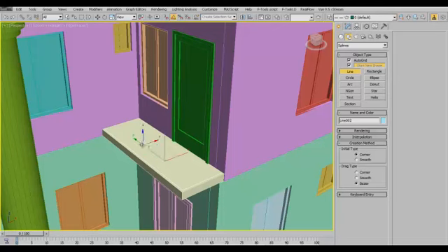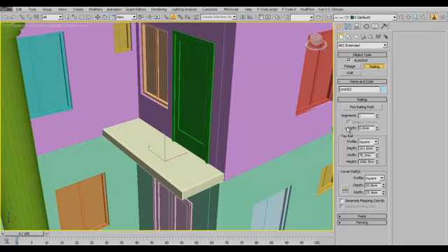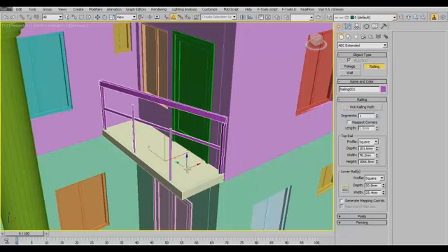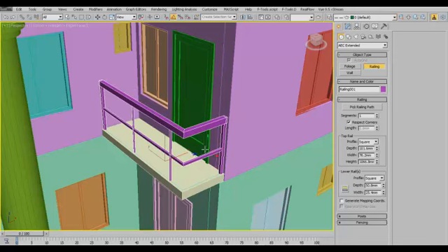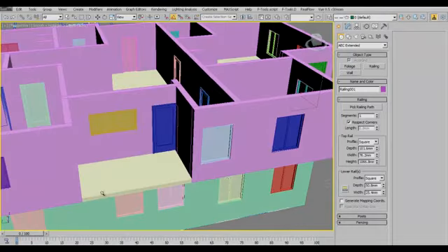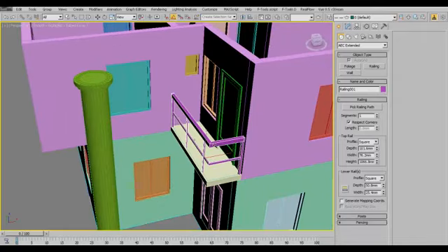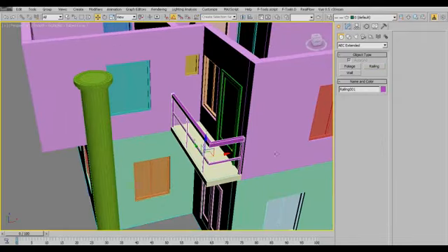So with that created, I can now pick my railing. To create that, I'll just say pick railing path, then pick the spline, and it doesn't look good now. So I'll tell it to respect corners, then it respects the corners, and fine, we have our railing there. The same way you create the railing right here, which I'll do later and not right now. So create a railing, then you exit the command with right click.